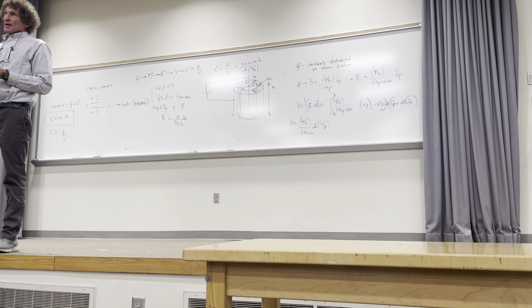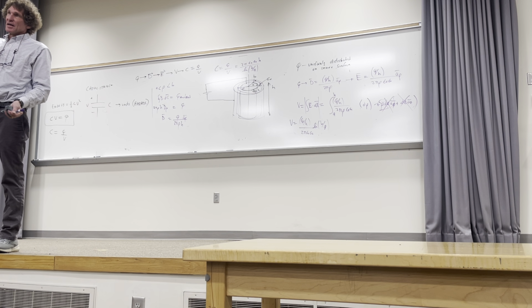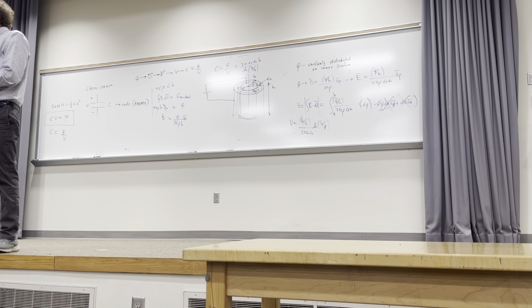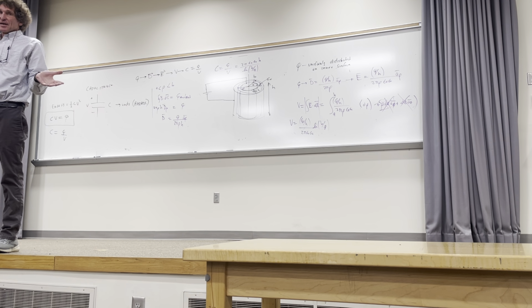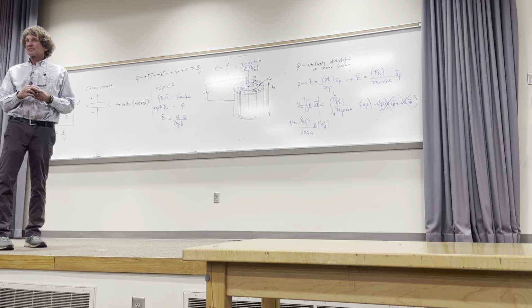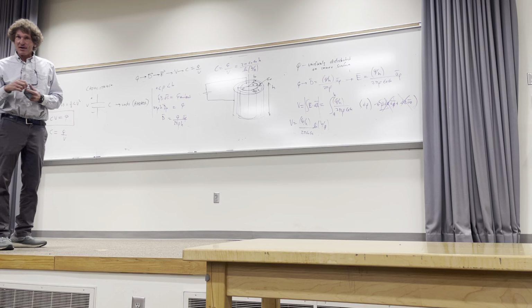Well, I was glad I didn't do this, but somebody didn't have proper circuit protection, and when they discharged the system, there's an inductance in the cabling that keeps the current going, and it ran the current through the capacitor, so it was developing a charge in the opposite polarity from what it should be, and the thing blew up and looked like a grenade went off. These are huge capacitors, and to heat some of those things enough to blow up is kind of scary. I wasn't there, but that's just something about capacitors to be aware of.